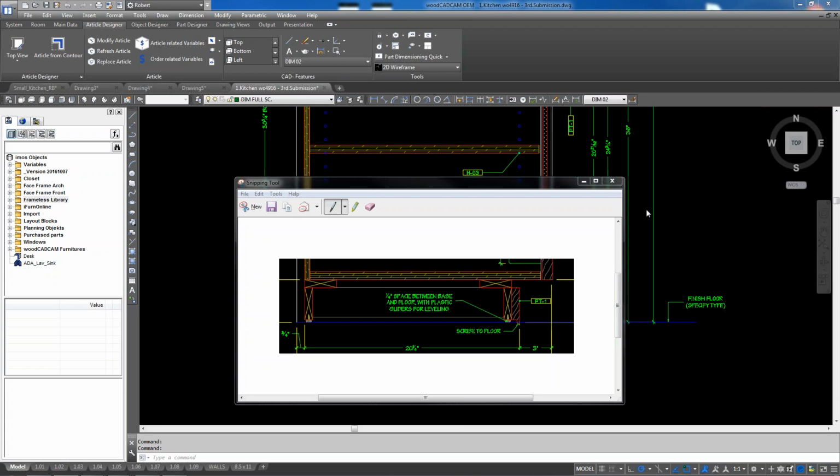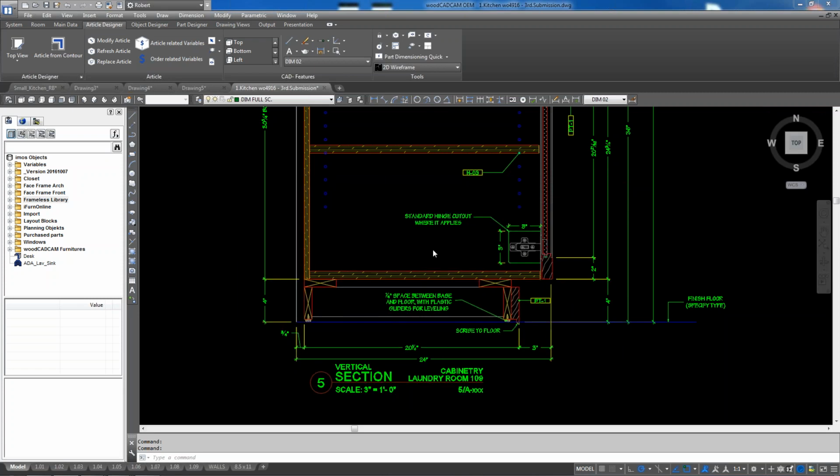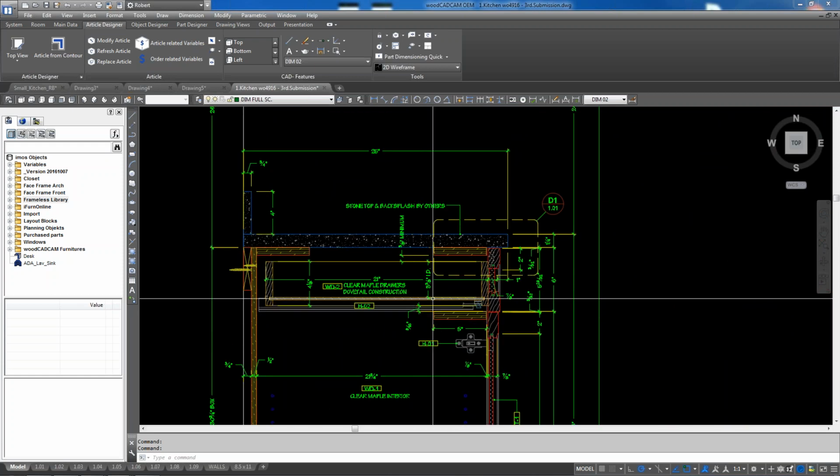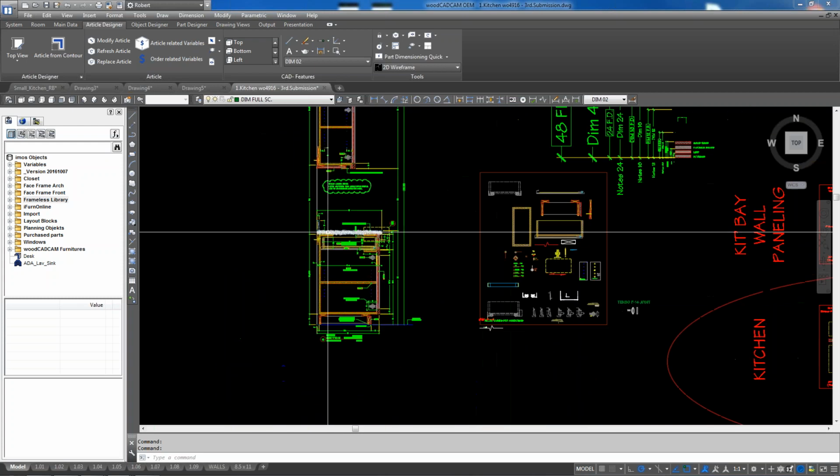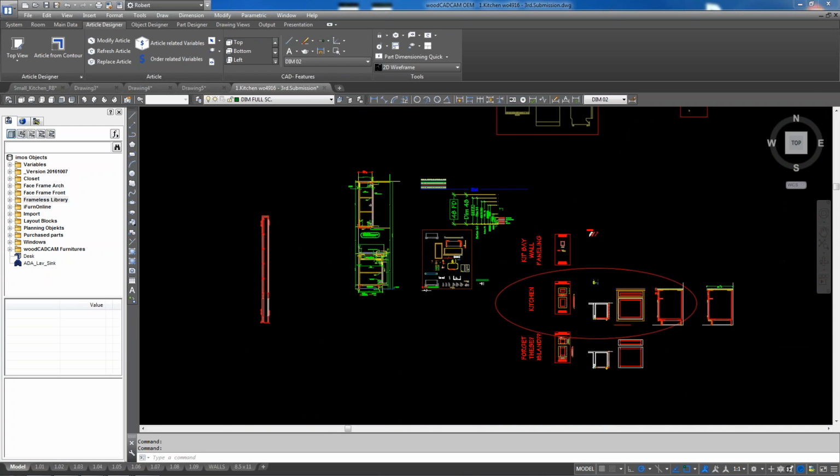All right, tell me about countertops. What's your typical countertop construction? Well, I guess, again, it depends on the situation, but most of the time it's stone by others. Then if we do it, I guess it would be 3/4 flat plywood, laminated from the bottom with, let's say, a 4 inch 3/4 strip, and then solid wood on the face. Is that correct? Okay. Yeah, but we don't use it too often. Usually it's a stone by others.